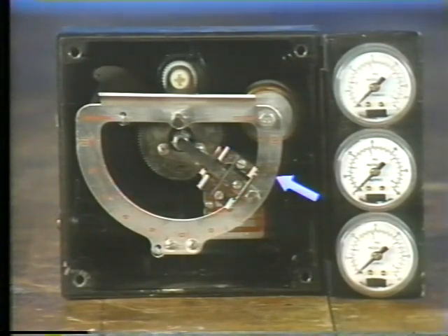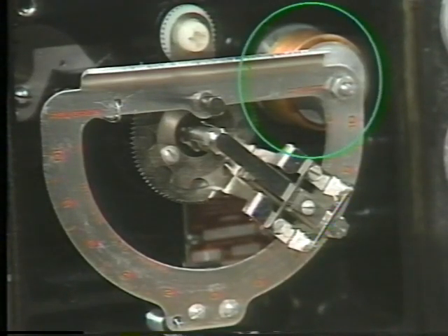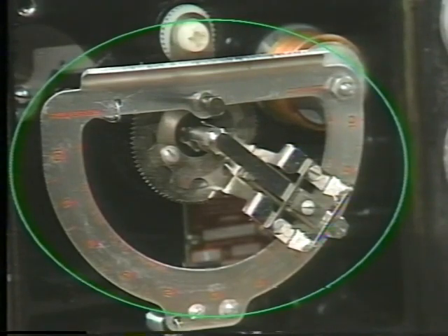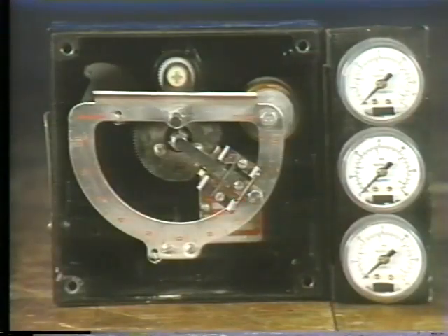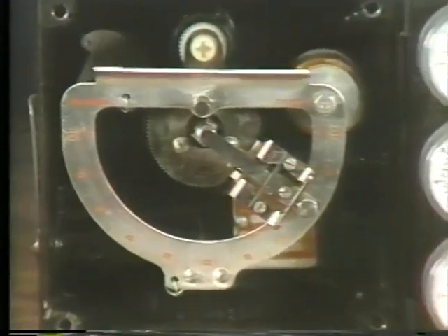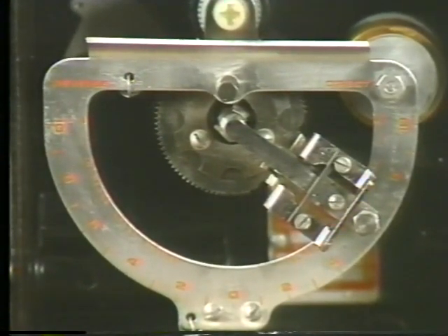Now, this balance beam is a little different than the one we saw in the force balance positioner. As you can see, it's in the shape of a half circle rather than a straight bar. And with this positioner, when the bellows expands and contracts, it pivots the balance beam, which moves the flapper arrangement either closer to or farther away from this nozzle. A unique aspect about this balance beam and flapper arrangement is that the flapper can be positioned so the positioner responds in different ways.